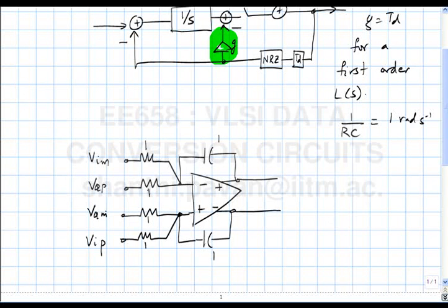All right. So, if all these resistors were 1 ohm as shown here, then the current flowing in through the integrating capacitance is proportional to VQP minus VIM. That's the current flowing into the top capacitor, and I hope all of you understand this. There's no magic here. It's quite straightforward. So the integrator is inverting, so the output here must be sampled. The input to the quantizer was always denoted by Y. So which is the positive Y and which is the negative Y?